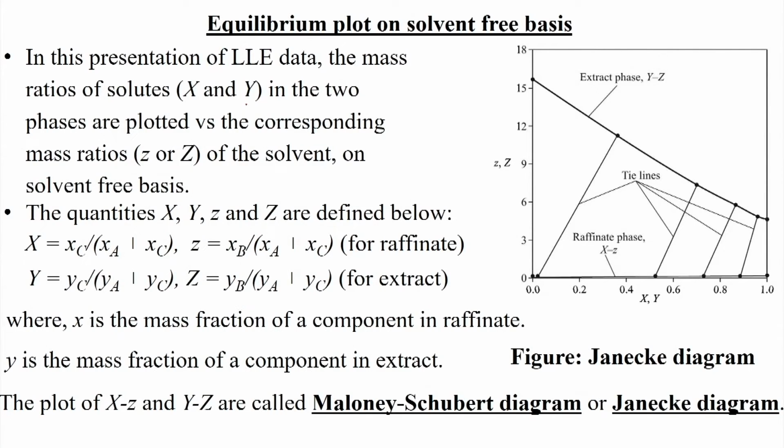We use capital X and small z in the raffinate phase, and capital Y and capital Z in the extract phase. All the values are on the solvent free basis. We will discuss the advantages of the solvent free basis calculation also.